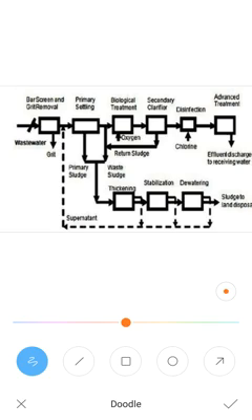First, the preliminary treatment process consists of separating the floating materials, such as dead animals, tree branches, papers, pieces of rags, and wood. Whatever is present in the sewage water or floating on the surface is removed, along with the heavy, stable inorganic solids.